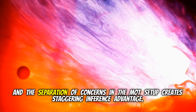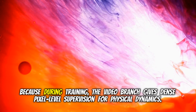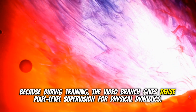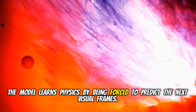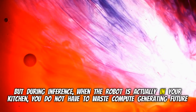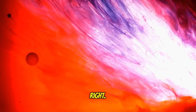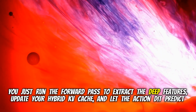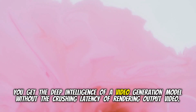And this separation of concerns in the MOT setup creates a staggering inference advantage. Oh, absolutely. Because during training, the video branch gives dense, pixel-level supervision for physical dynamics. The model learns physics by being forced to predict the next visual frames. But during inference, when the robot is actually in your kitchen, you do not have to waste compute generating future video pixels. Right. You just run the forward pass to extract the deep features, update your hybrid KV cache, and let the action DiT predict the motor movements. You get the deep intelligence of a video generation model without the crushing latency of rendering output video.